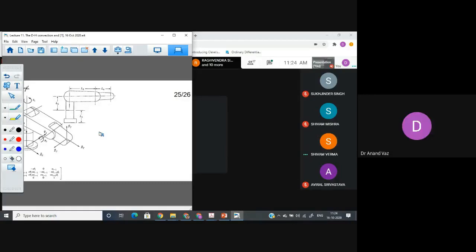In fact, you can use three revolute joints, all co-located, with their origins at the same point. You can go step by step, just like how we did. We produced these four reference frames, and then we did a transformation from one to the other to the other. In the same way, you can also do it for a spherical joint. It can be done.